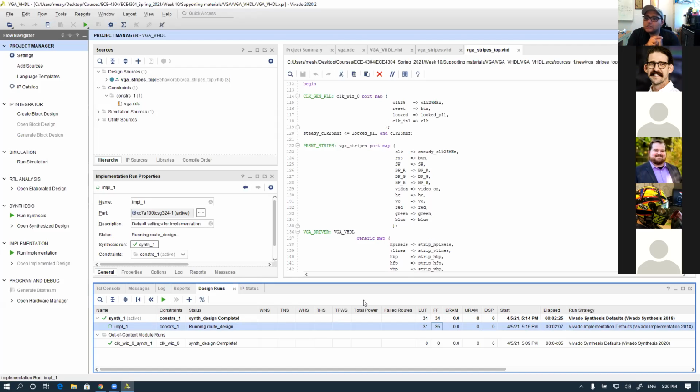In partial reconfiguration, the FPGA looks like a sheet. You start breaking the FPGA into portions, and then you make a constraint on this portion and say that this design has to fit in this portion. Don't ever talk to the others randomly. Then it is considered like mini FPGAs inside the FPGA. And we use something for this called a floor plan. Have you guys heard about it? It's called floor plan.